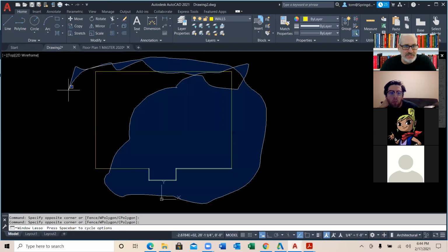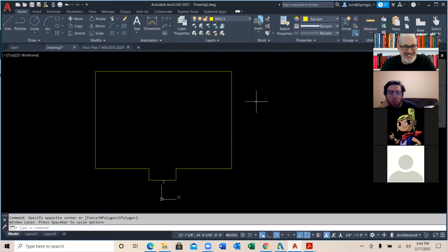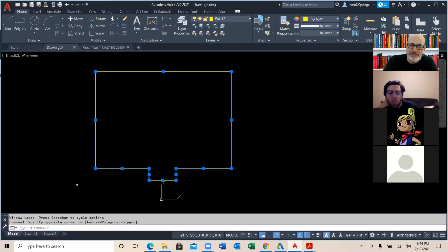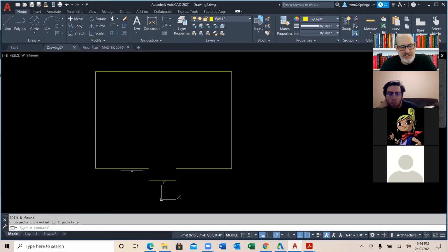I can go ahead and do this and hopefully do this. Doesn't work too well. I can go this way. And so I do that. And then I just type in the letter J. J for join. Type in J and hit enter, boom, and now that's all joined together.